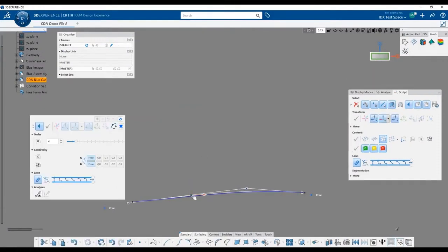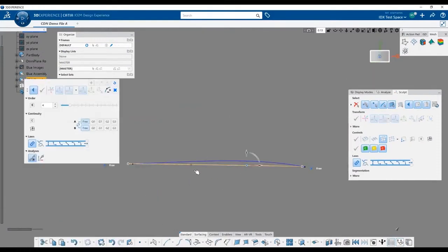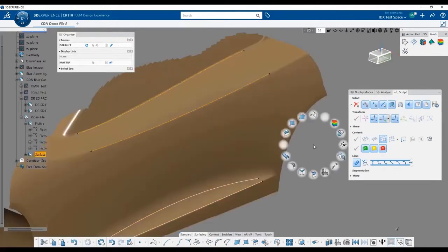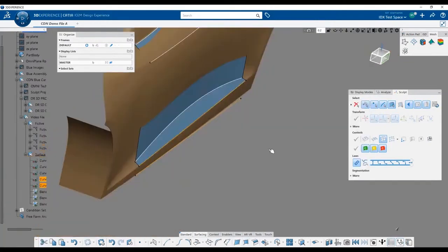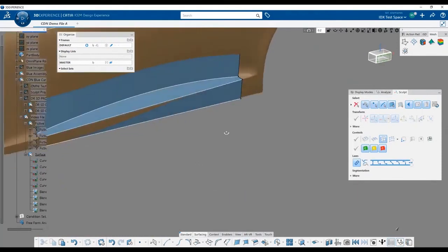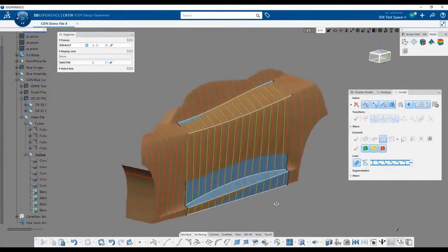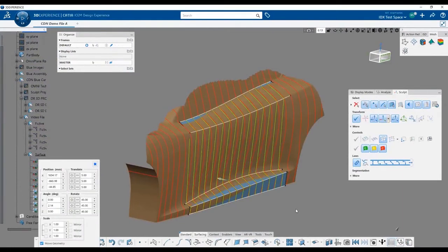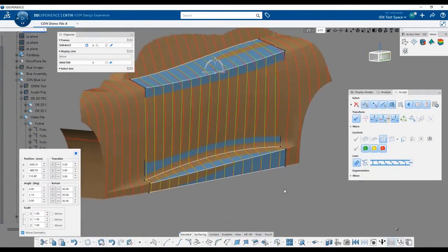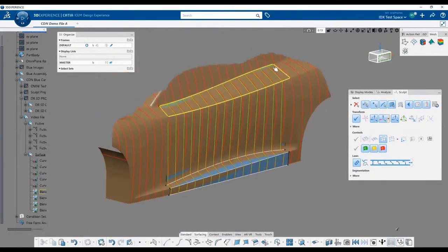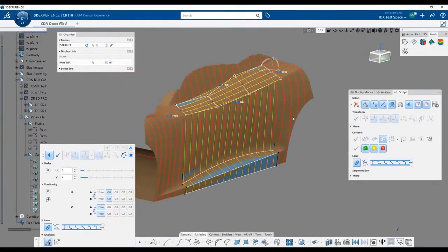Next, we'll create temporary display lists for each fictive edge reference curve in order to create accurate new OmniCurve guides that will associate our main slab surface edges with our newly created Bezier curve lines. Now we'll create our main surfaces using Omnisurf. This is a single surfacing tool that creates a surface based on the elements you select. Because we selected only 2 rails as our construction elements, the result could only be a blend surface.